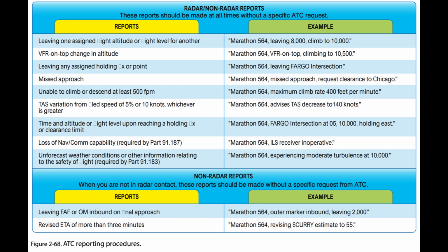5. Type of flight plan, not required in IFR position reports made directly to ARTCCs or approach control. 6. ETA and name of next reporting point. 7. The name only of the next succeeding reporting point along the route of flight. 8. Pertinent remarks.